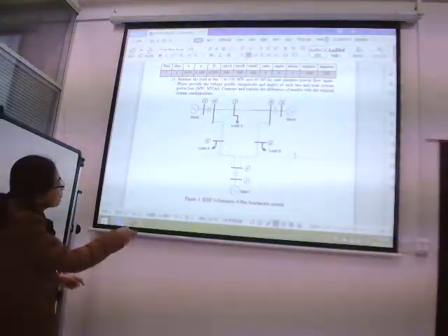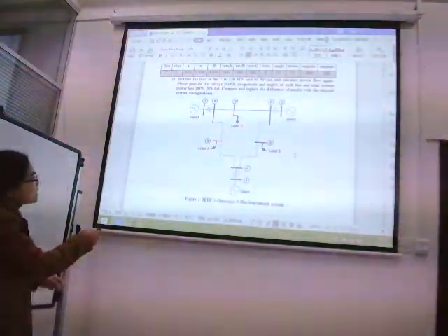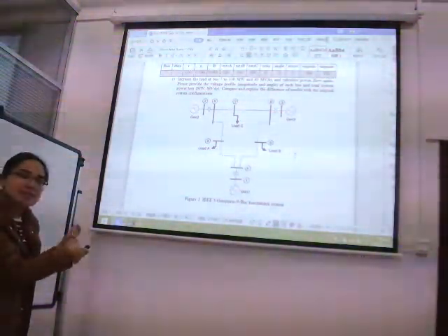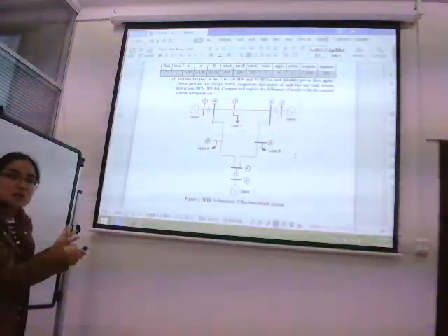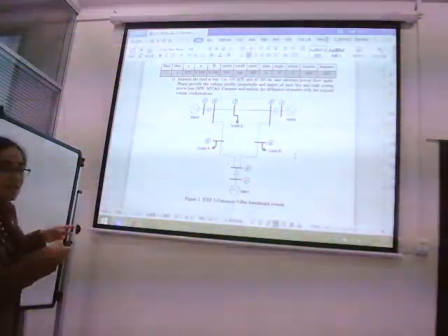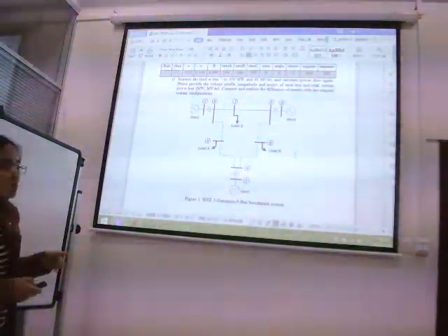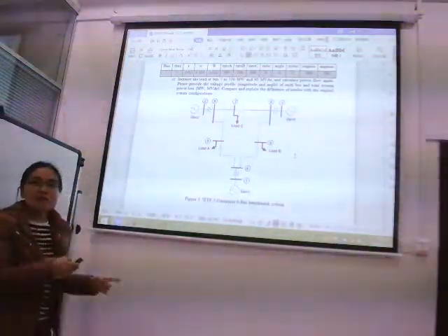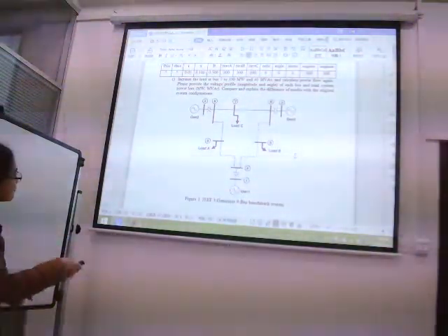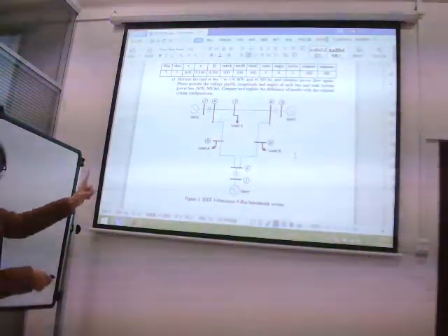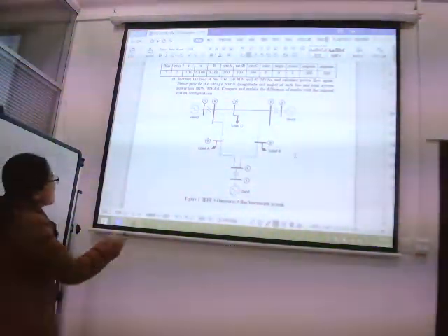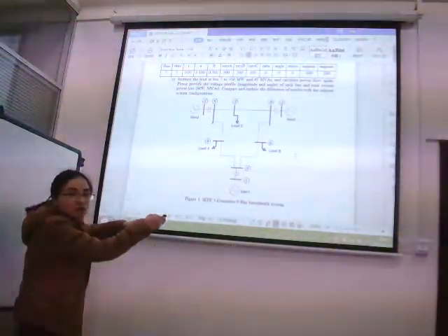We have to transfer power from here and here. And for this line, we only have 1 load demand, that is in bus 7, but we have 2 generators to provide the generation, that is generator 2 and generator 3. So this is a waste of power, because in this section we only have 1 load demand but 2 generators. But for this section, we have 2 load demands but only 1 generator. To satisfy the system generation and demand, we have to transfer power from here to here.